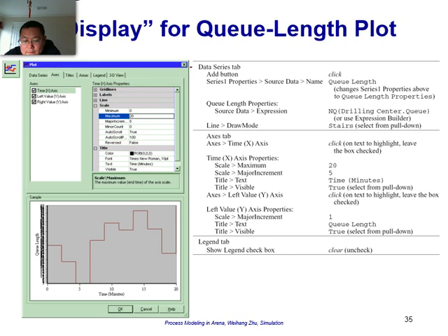This is a dialog box for defining the plot. There are many options, but most of them are self-explanatory. The most critical thing is to define what parameter you want to display. When you click Add or Edit, you will see the Plot Expression dialog box. It allows us to add the expression. Some expressions may have been figured out and suggested by Arena. If you want to have more, you may use Expression Builder to define more specific expressions.